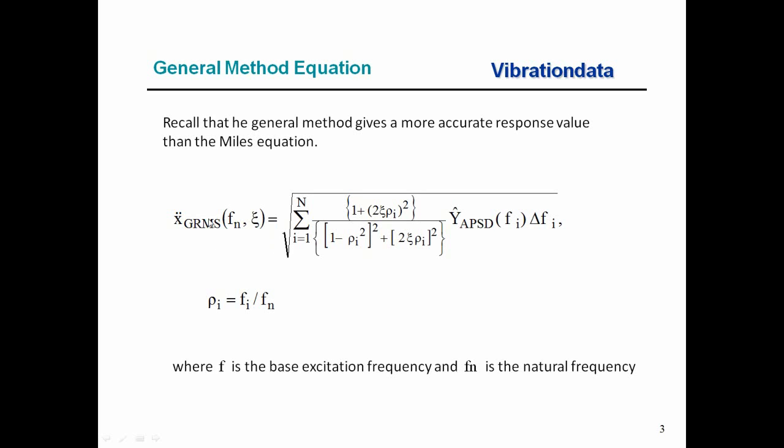And again, on the left side, we have the overall response acceleration. This is the absolute acceleration. And in addition to depending on the base input PSD, it also depends on the natural frequency of the system, and then in this case you have the viscous damping ratio, or you could think about it in terms of the equivalent Q value, where Q is the amplification factor. So embedded in this equation on the right hand side, this is the power transmissibility function, and we talked about that in the last webinar.